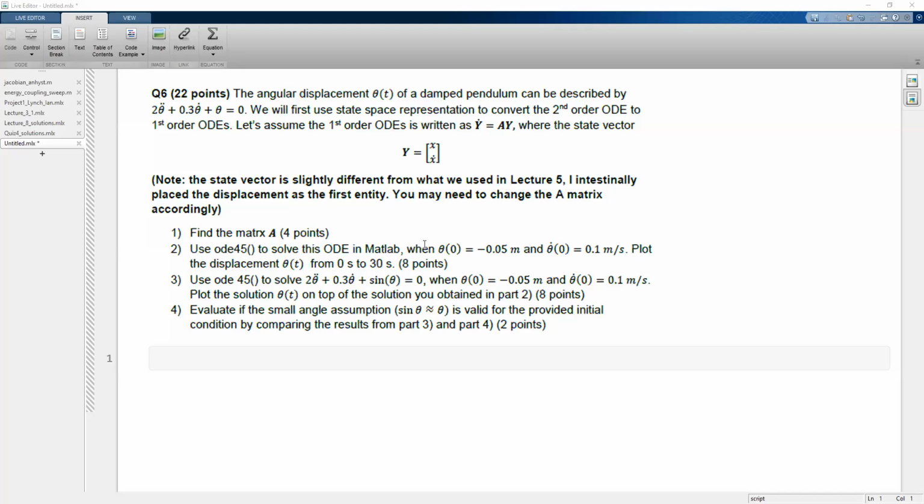I forgot to mention. When you calculate this shaded area, you have to make sure your system has reached a steady state. So that loop is a steady state loop. You have to truncate the transient response before you plot the loop. Okay, cool. And then of course we'd want to make the force a function of time, and then use that as our x-axis, and the y-axis as our steady state response, right? Yep. Awesome. Share screen. Okay, here's the screen. That's the correct screen. So that's clue number 6 in example 1.